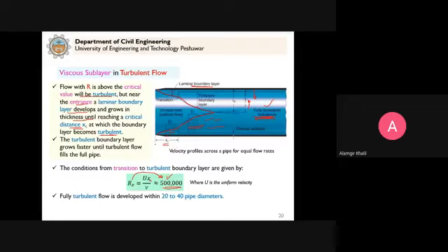The entrance length L. In simple words, you see the full turbulence that forms here. As we can write down the equation for the laminar flow to calculate the entrance length L, where we have the fully developed laminar flow. Now in this case, our book says that for fully developed flow, there is no single equation because of the turbulence that is changing with the conditions. So that's why it says that it occurs within 20 to 40 times the pipe diameter. This is given in our textbook.